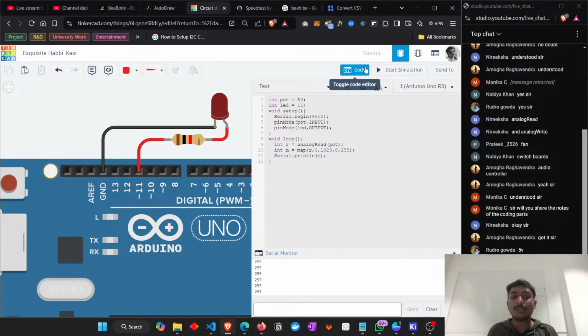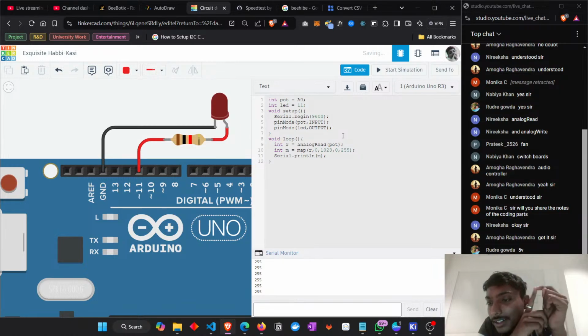Right. Now, we learn about the analog read. Now, if I try to mimic that PWM signal, what am I trying to mimic? Analog signals only I am trying to mimic, right? So, what function should I use to mimic that analog signals? Now, we learned if you want to write something in digital, you will be doing digitalWrite. If you want to read something, you will do digitalRead. In analog, we have done analogRead, which will read the value of the potentiometer, right?